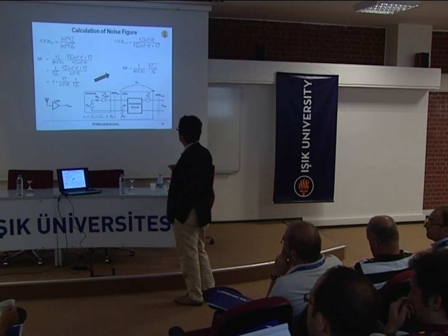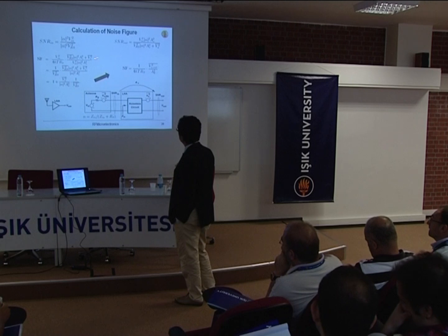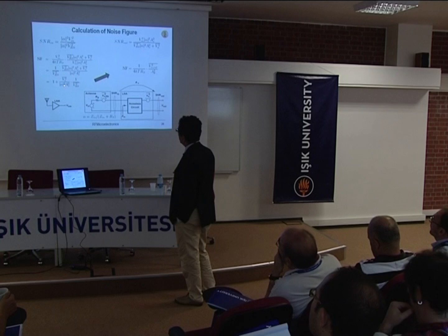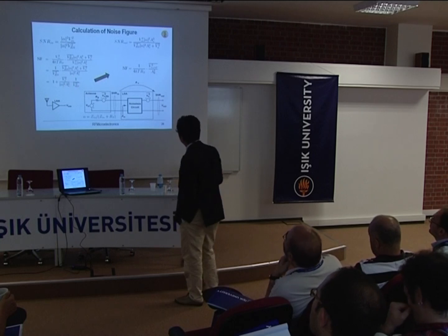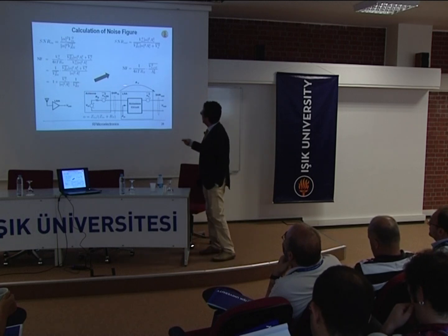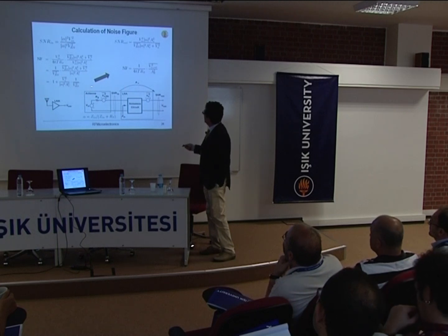we input signal to noise ratio over output signal to noise ratio. So we just write V squared RS as 4kT RS, and we go on elaborating this expression. At the very end, we have 1 plus V squared N over alpha squared AV squared, 1 over V squared RS. We group everything under V squared RS, so 4kT RS, and we find what? We find alpha squared AV squared V squared RS plus V squared N, which is the output noise.